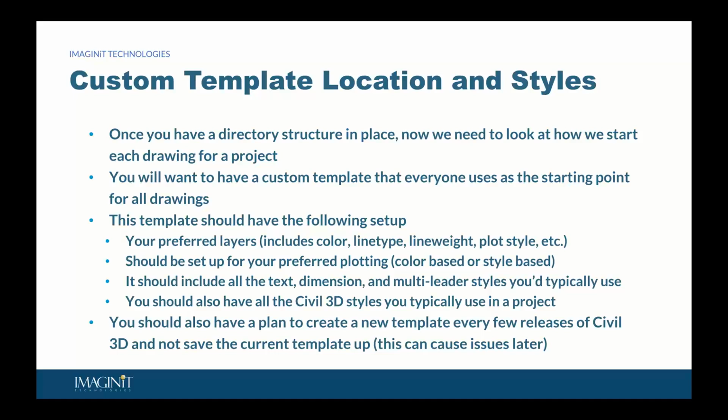I run across a number of people that have had Civil 3D templates dating back from 2011 and 2012 that they've just simply carried up. The problem with that is those templates tend to contain a lot of garbage information, things that are no longer used by the DWG format, things that are no longer used by Civil 3D, and now we have extra stuff in that drawing that can cause problems later on down the road.